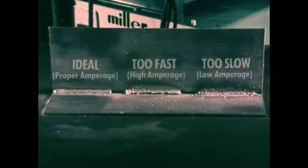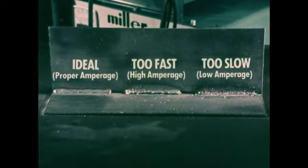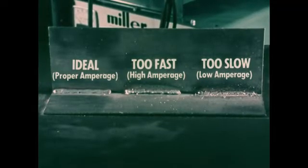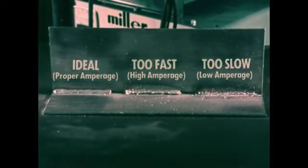An examination of all 3 weld joints shows clearly that too high a wire feed speed will tend to produce spatter and a high crowned bead. Too low a wire feed speed tends to produce a small bead with spatter and inadequate fusion. When the amperage is right for the condition, the bead is of the desired size, properly flat, spatter is held to a minimum, and the arc will sound smooth and steady.